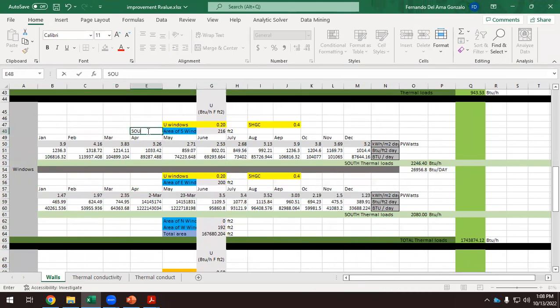That was the south. This is the east. Okay. And well, basically, I don't have to do anything else because remember that the first row is just this one times 337. Here we just convert kilowatt hours per square meter to BTU per hour per square feet. Okay, so make sure that we always have this cell and then times the 317. That's just for converting units.